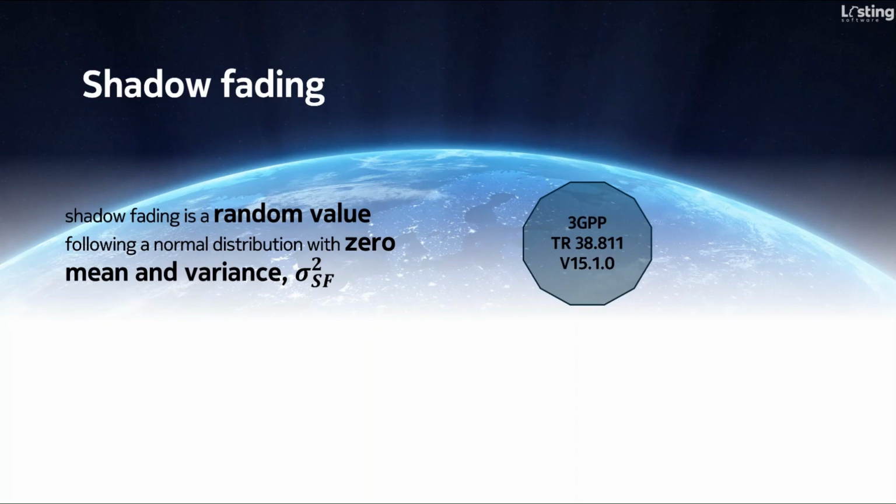Attenuation due to absorption in atmospheric gases depends mainly on frequency, elevation angle, altitude above sea level, and water vapor density, and can be neglected at frequencies below 10 gigahertz. However, for low elevation angles, the slant range has a significant part in the atmosphere, and attenuation by atmospheric gases can then be significantly important for frequencies above 1 gigahertz.